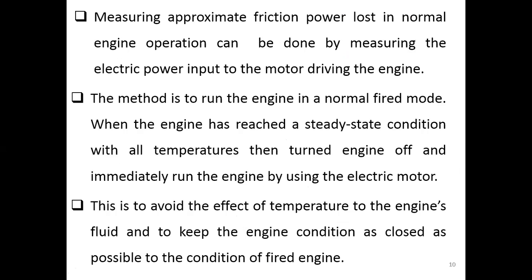Now, to find out the friction loss from the engine, we can use an electric motor to drive the engine. We first run the engine at fire mode. Fire mode means we run the engine as it is normally run.